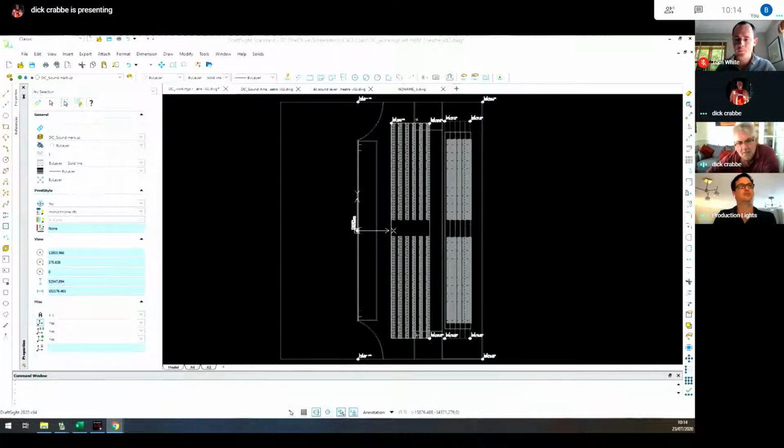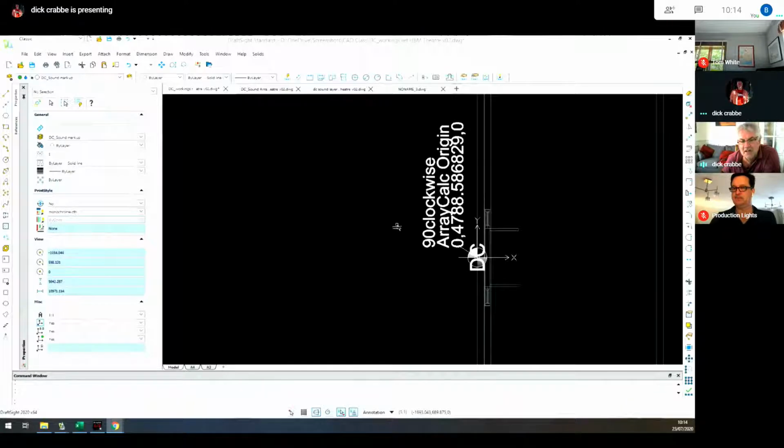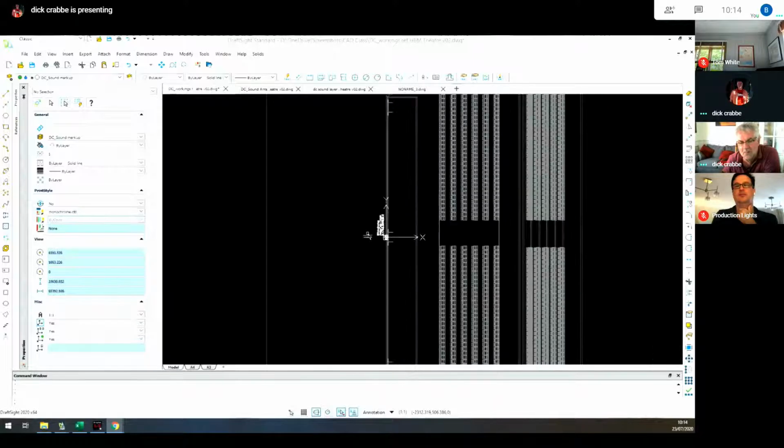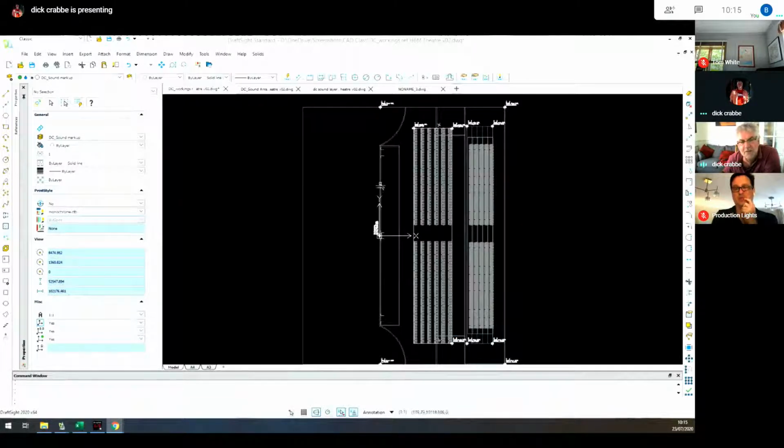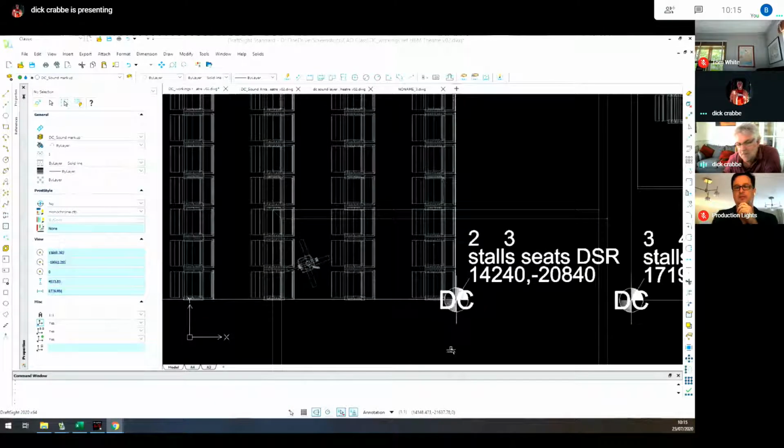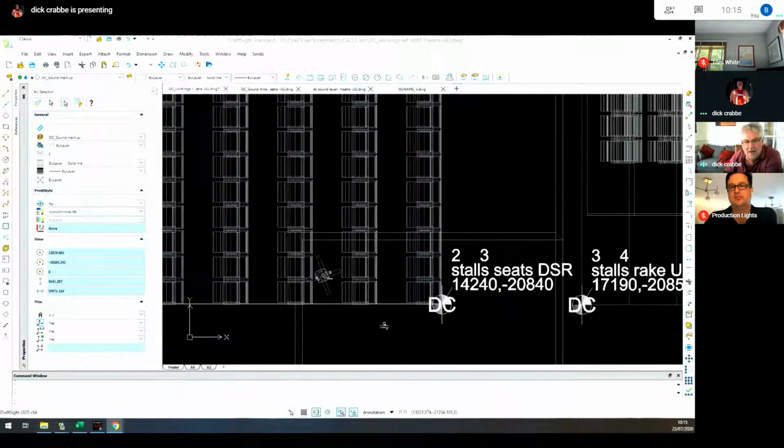I've imported Dominic's raw drawing. I've XREF'd it in. I've flipped the orientation and moved the origin because I'm going to show how it works with Array Cut, which is d&b's loudspeaker program. L-Acoustics have another one. I've put myself a little note here, so I'm using this as my 0,0 reference downstage center, and the coordinates, how to drop it back into Dominic's original drawing. I've put in some various points here around the place. These are blocks. So this is an idea that Sharon showed us a couple of weeks ago about coordinate blocks. And you can drop them in to produce yourself.